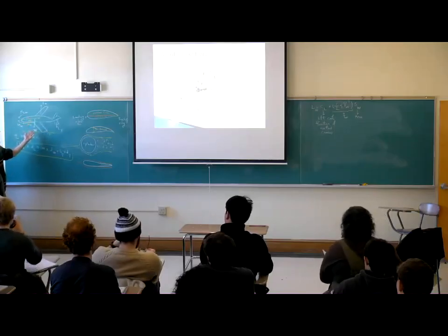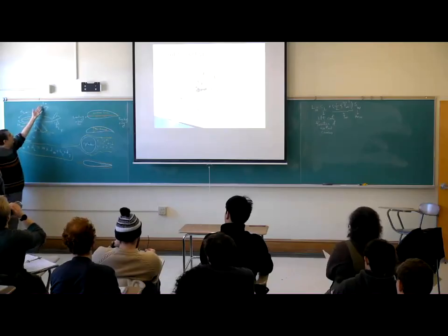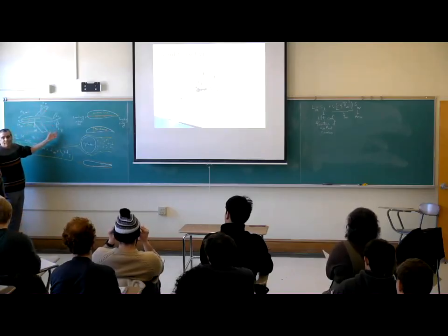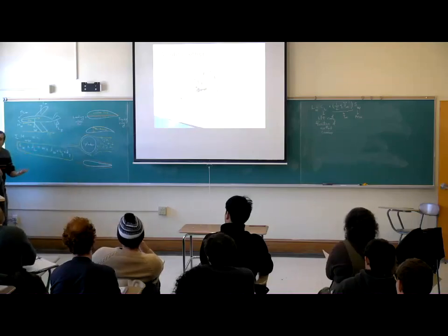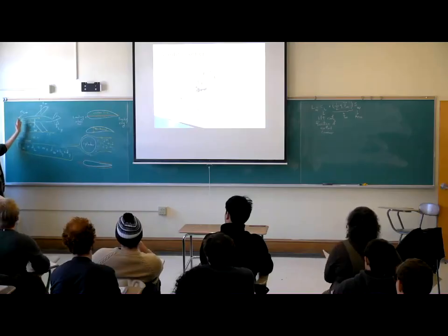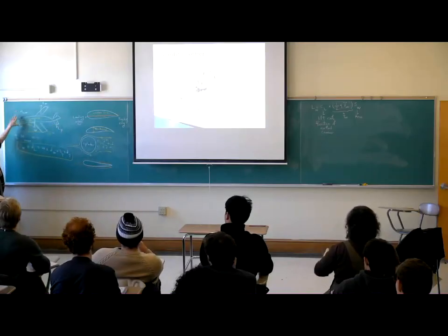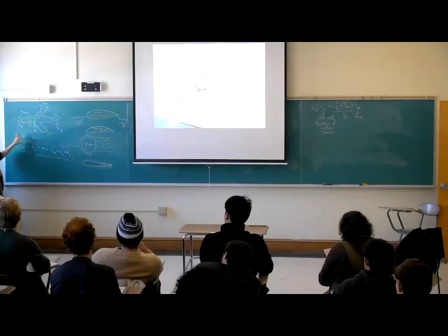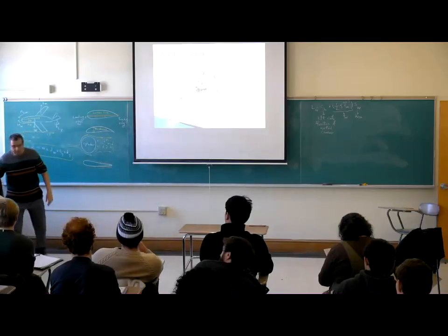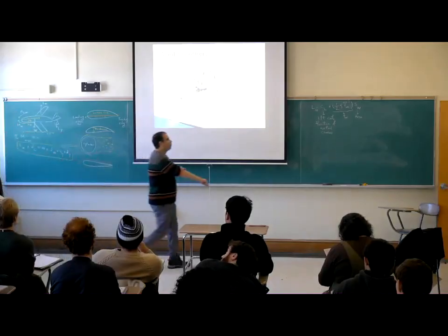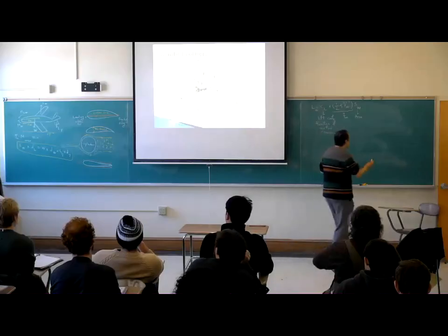I cannot play with the weight. I may play with the lift of the wing or the lift of the tail. The standard is that when there is an upward gust, you play with the lift of the tail such that it returns back in the downward direction.